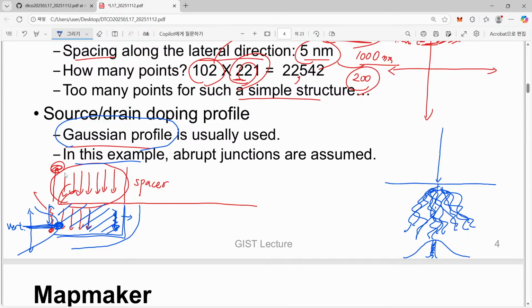However, there is no certain way to make it exactly at, for example, 10 nanometer. We cannot stop them exactly at 10 nanometer. On average, they can stop at 10 nanometer, but some of them were lucky and go deep inside this substrate, and some of them are just hanging around and are found much closer to the interface.